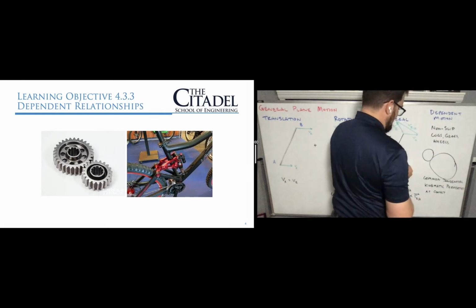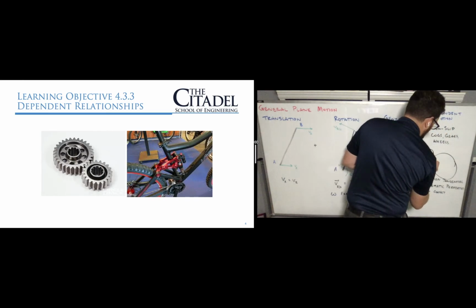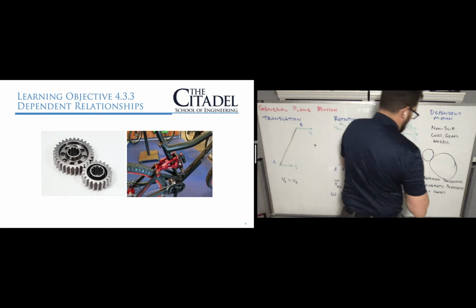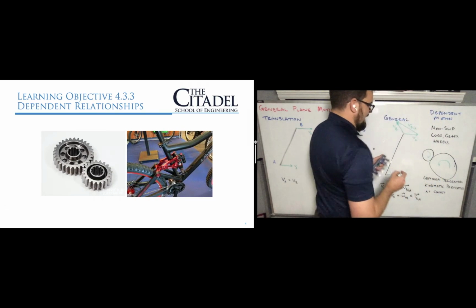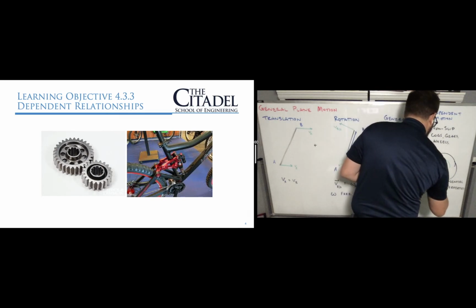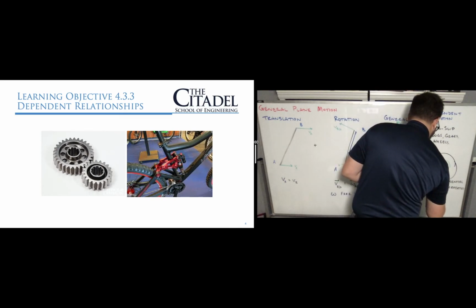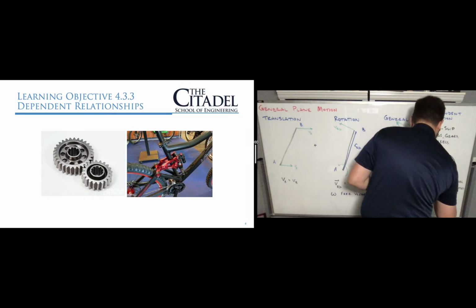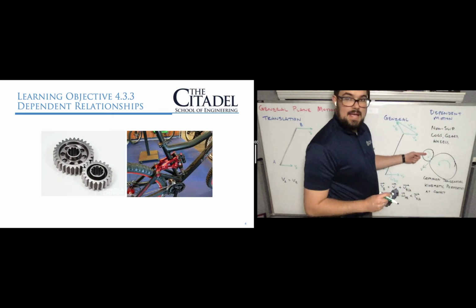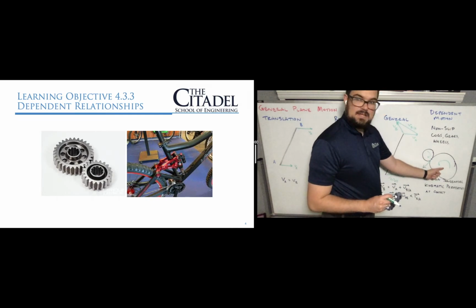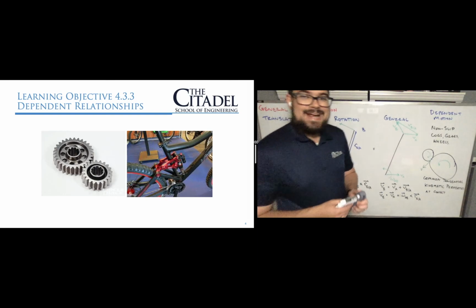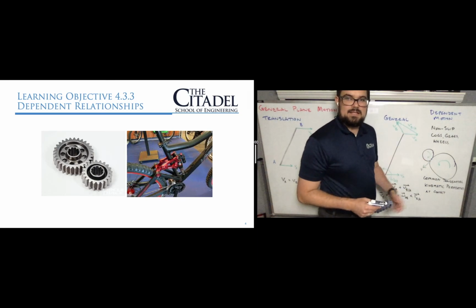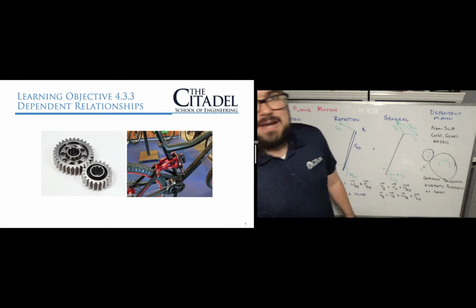And so what that means is that here we have this contact point. If these 2 gears were rotating, something like this, at that point, that velocity is going to be the same, because remember, all of the velocity points in the tangential direction. And so we can think about moving from a non-moving center to the velocity, and that'll give us one equation, or from the other center to the velocity, that would give us another equation, but they're going to have the same velocity where they touch, common tangential kinematic properties.